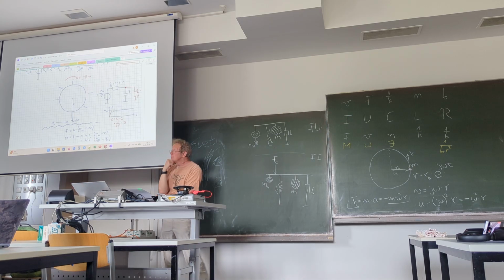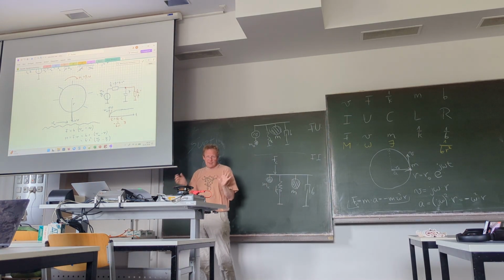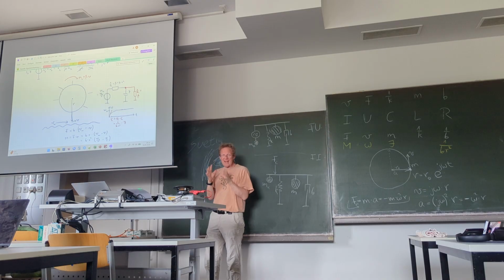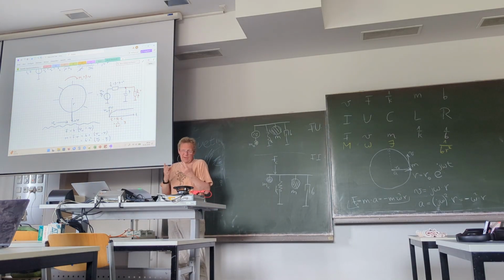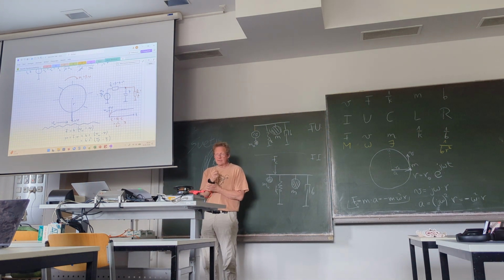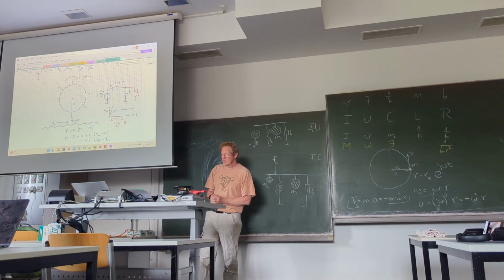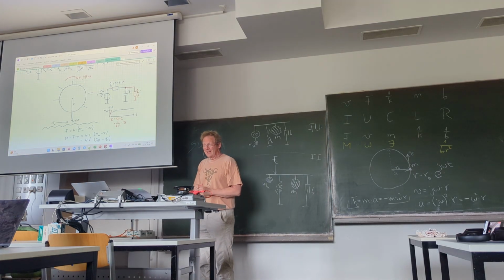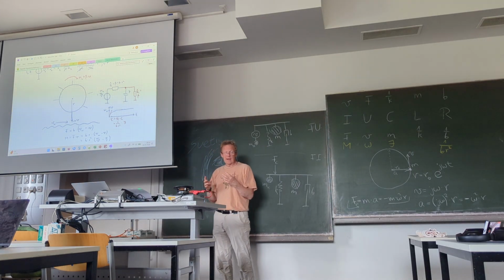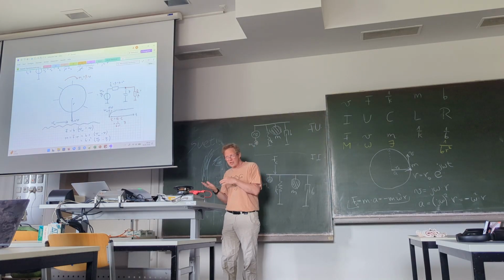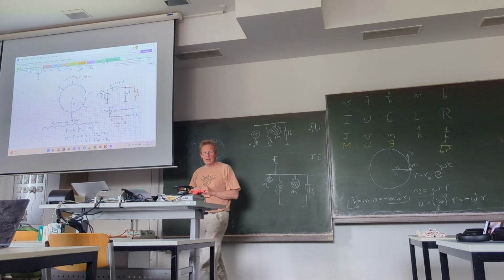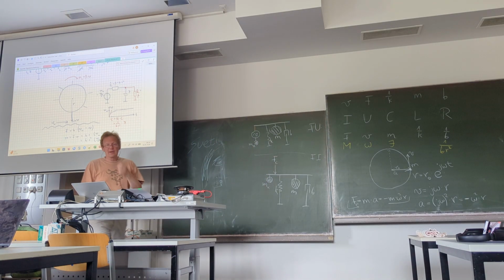And a very nice simplification is always when you're talking about static situations. Capacitor, inductivity, they're always dynamic components. So it's only interesting if something changes. Either the current changes or the voltage changes, but if there are no changes, you can just neglect all capacitors.